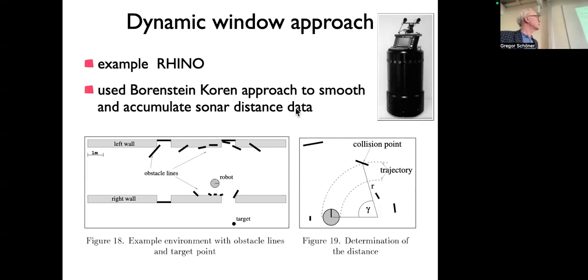Yeah, so this is an example of this working. This is a robot that uses sonar to get distances, so it's also not very reliable. And the target, I think, was also dead reckoning. This is a system that keeps tracking where it is and just knew where it wanted to be. So here, it's like the demo I showed on the attractor dynamics approach, right? Where the target is somewhere on the other side of the wall, and the vehicle runs along the wall, always repelled by the wall, until it finds the opening and goes in. That's sort of the same idea.